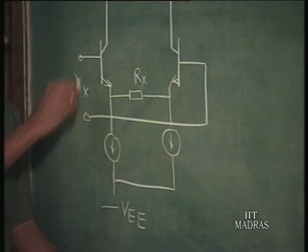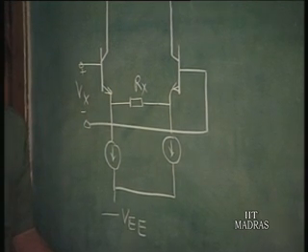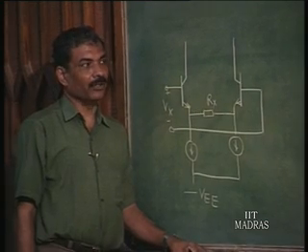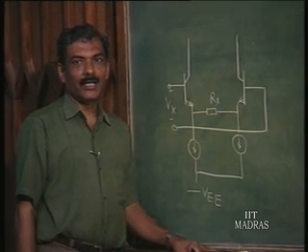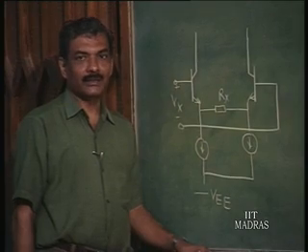This circuit, as is shown here, is the circuit which is able to convert a voltage into the differential input current required for the Gilbert's gain cell. After all, most of the signals that are available to us are going to be voltages.